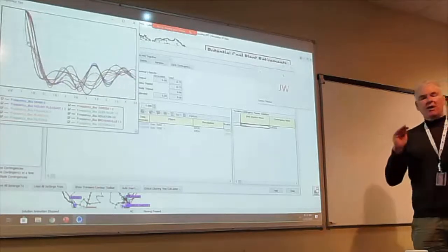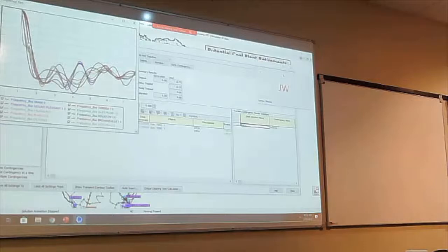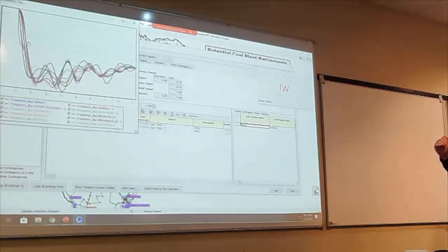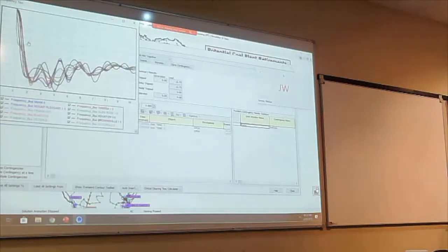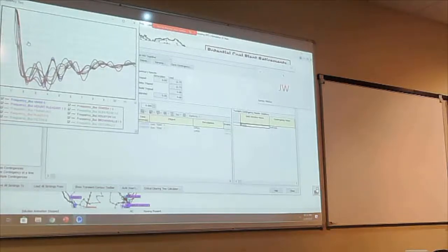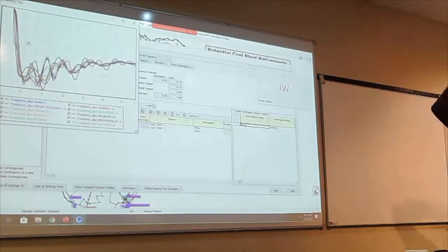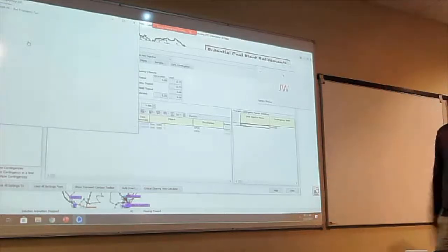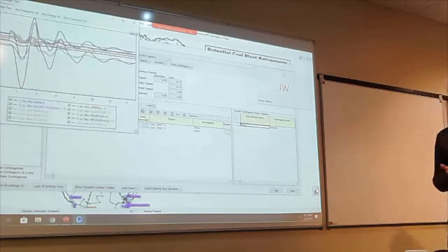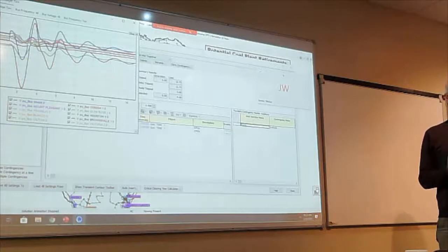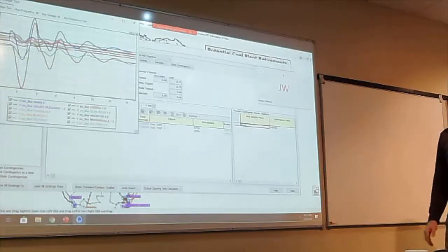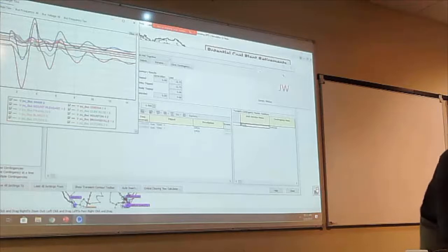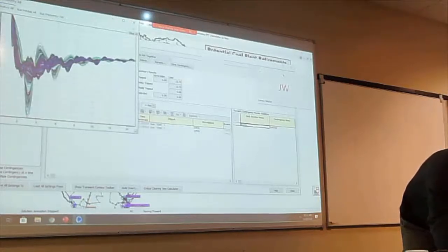After it runs, the next step is we're going to do modal analysis on some signals. As I said, there are 3 different ways to get into modal analysis. One is to use the icon at the top, in the add-ons next to the transient stability. You can load data from plots there, or you can load data from other files like a COMTRADE file. We're going to go in just from the transient stability results.